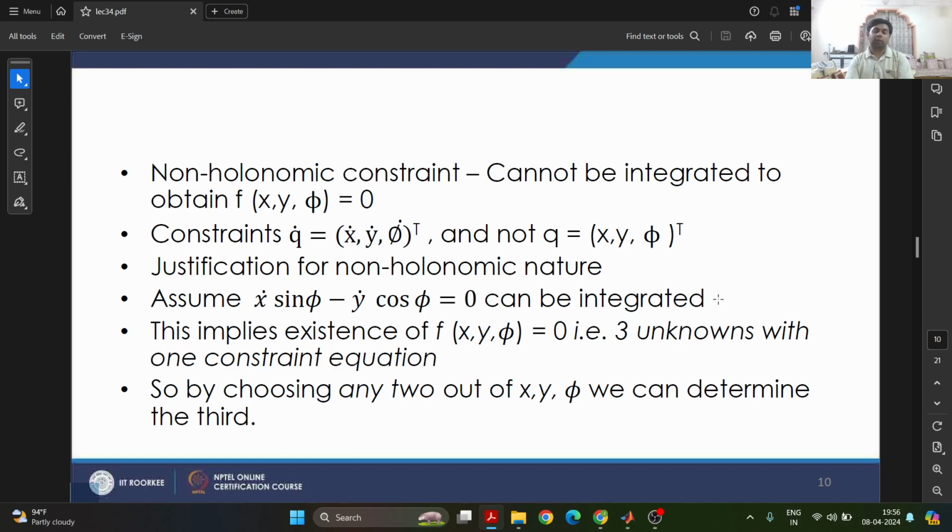Yes, in a way you are right. So every object will have 3 degrees of freedom: x, y, and rotation. Whereas the car can take a turn or can only move forward. It is non-holonomic. Whereas if you watch the videos on Omni wheels or Mecanum wheels on YouTube, they will show these robots can move in the x direction, y direction, and they can also rotate. So all the 3 degrees of freedom they can achieve.